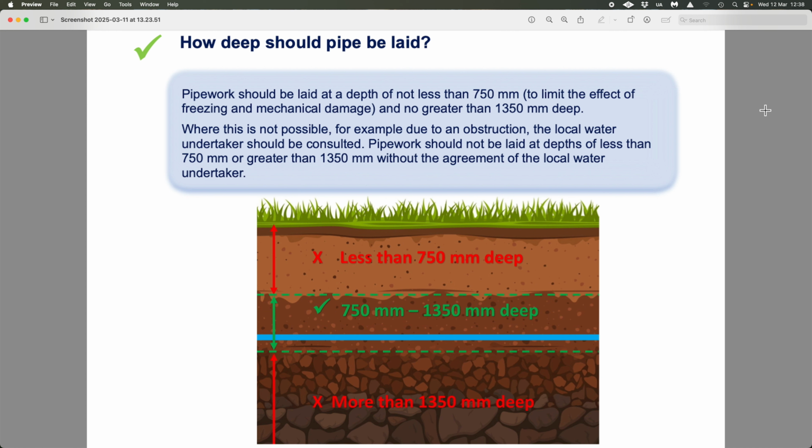If we put that and we utilised, let's just say you were doing an upgrade from a system only boiler to a Combi boiler. I'm not sure why you would do that these days, but if that's what you wanted to do, you will likely have a cold water storage tank within the loft space. If that is the case, as long as that tank is a GRP rated tank and it's got good insulation on it, stored water will generally sit within that tank at around 15 degrees.